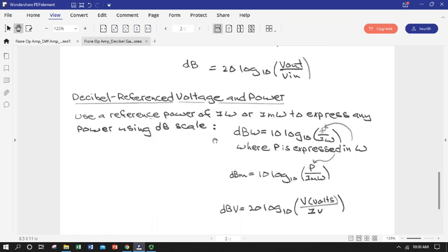Maybe you're using a space heater to keep your feet all toasty while you listen to this lecture. And you look at it and you could express the watts power output on the decibel scale by assuming some reference, probably of 1 watt. Maybe you have a 1,000-watt heater or a 100-watt heater. So you'd put 100 in the top for P, you'd divide by 1, so log base 10 of 100 would be 2, so you would have a 20 dBW heater, which is the same thing as 100 watts. So again, the W out front here, dBW, is telling you that your reference is 1 watt.